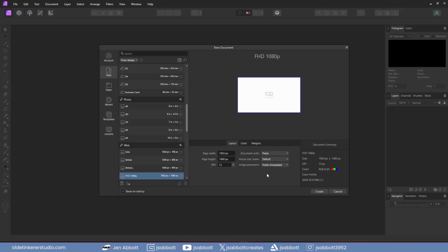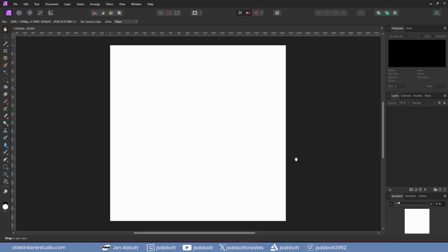A perforated metal texture is simply a black and white image where black areas are transparent and white areas are opaque. Open your imaging software of choice and make a 1K or 2K texture. Make a background layer that is white. This will be the metal.